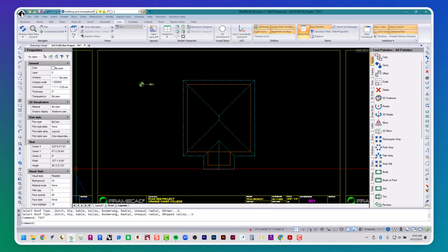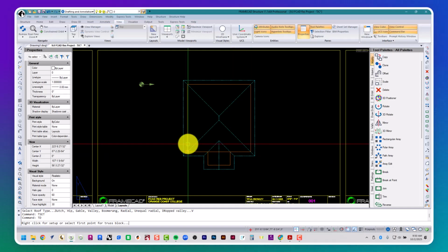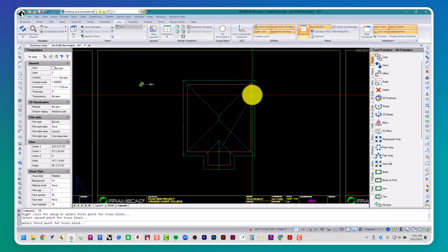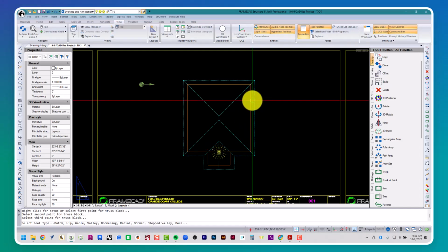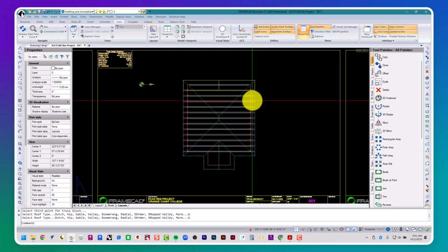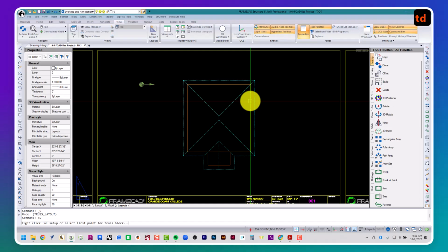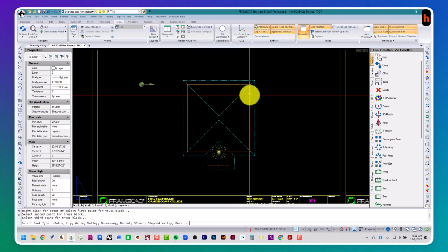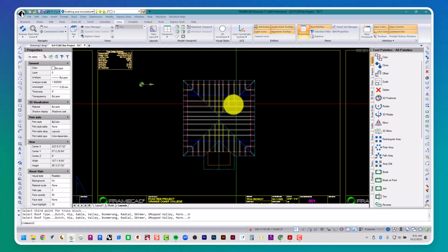We're going to add our trusses. Type TD for truss draw. For the first corner, we're going to choose this endpoint where the support lines are, this endpoint, and our third endpoint over here. We've got a G for a gable roof and a, excuse me, I'm going to undo that. TD. Click these 3 points. H and H. There we go.